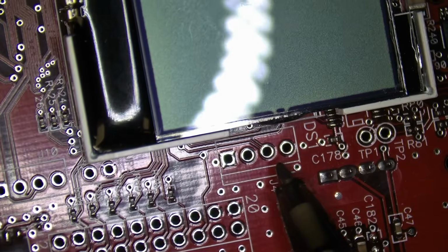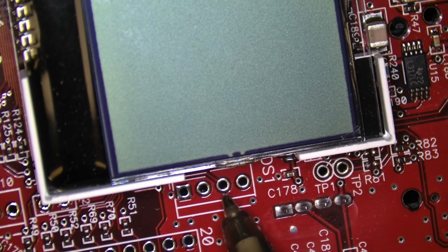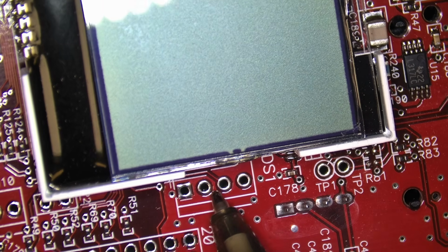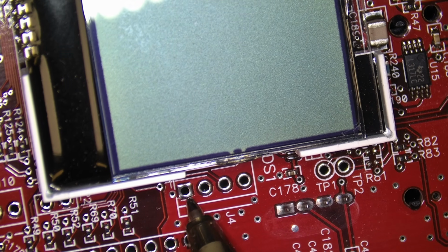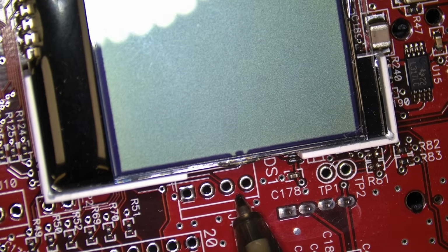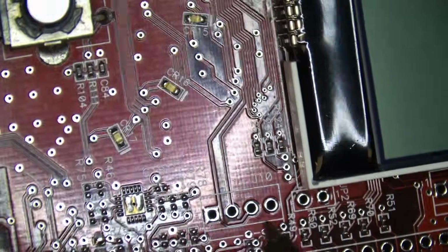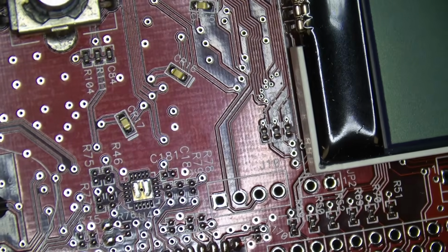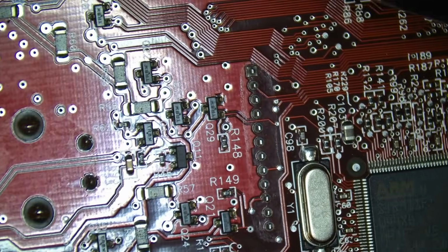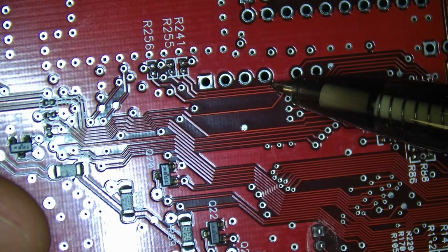And this guy over here, I see a connection to this guy, not to this guy, and this guy here looks like it's ground. That might be some other type of programming port. I would say this one here is UART. So guys, these type of things are all over the place. Right here is the backside. You can see what it looks like.